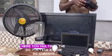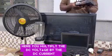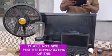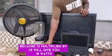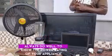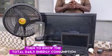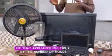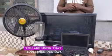So here you multiply the DC voltage by the DC current. It will give you the power rating of this decoder, because 12 multiplied by 1.5 will give you 18 watts. So always do well to know the power rating of your appliance, then to know the total daily energy consumption of that appliance, multiply by the number of hours you are using that appliance per day.